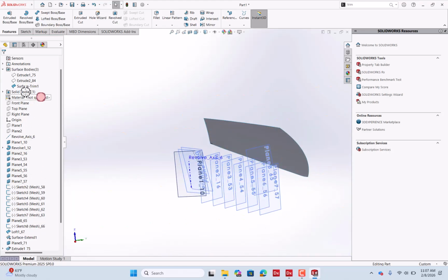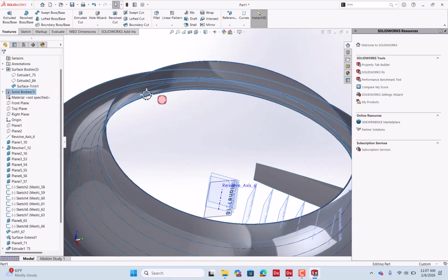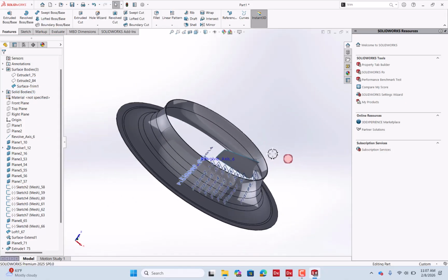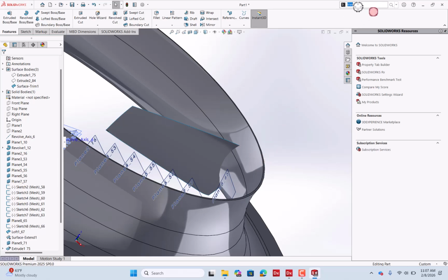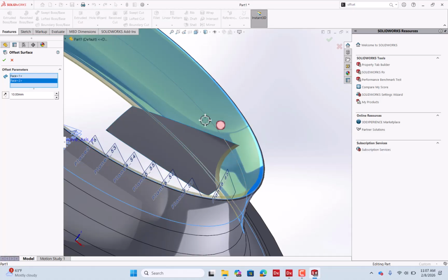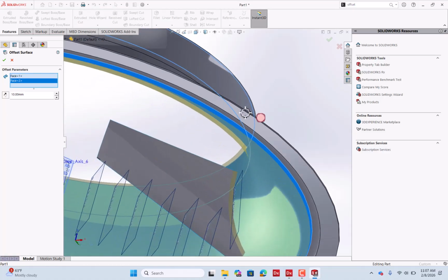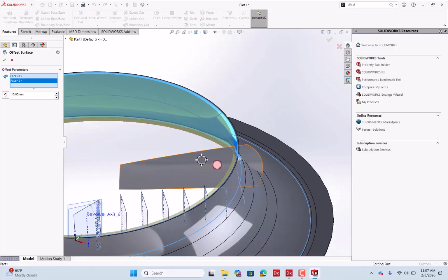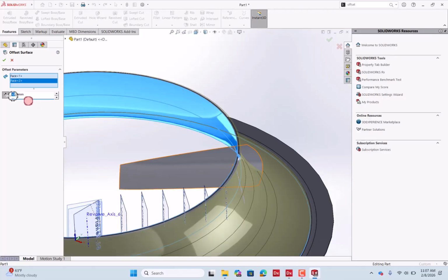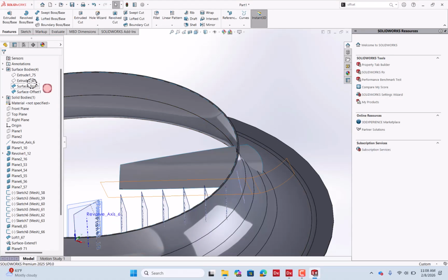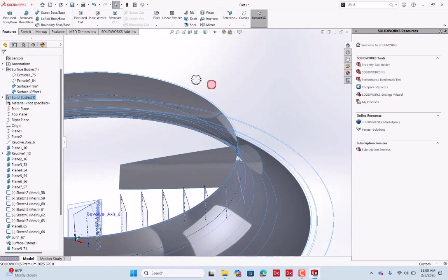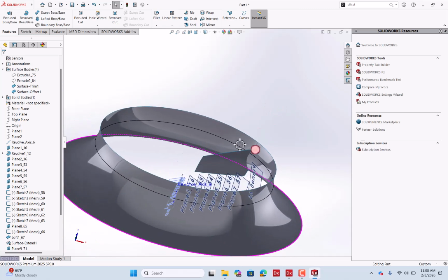Following this, you can certainly choose to show your solid, and you can finish the modeling here. In other words, you can use a surface offset, and you can select the faces you need to extract for the offset, which would be these two faces, and you can give it a small gap like 0.125 mm or 0.25 mm, and you can extrude it correctly, following which you can use the offset surface to trim the blade.